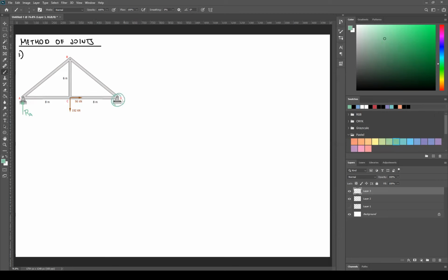Here on point D, we have a pin. A pin has both perpendicular and parallel reactions because it can support or resist motion parallel and perpendicular. So we have two reactions here, and then similar to your roller, you're gonna assume direction. I'm gonna assume the perpendicular portion of its reaction is upward, and then let's call that RDV because it's vertical.